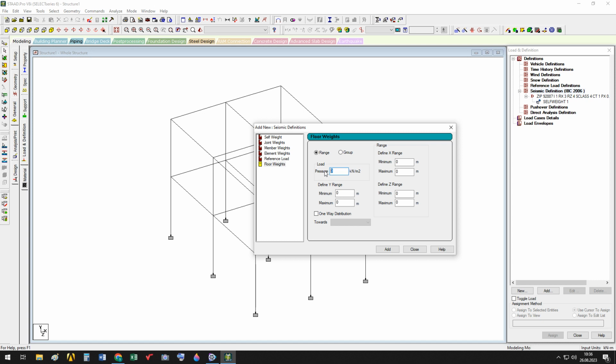Let's say, now I will show you how the lateral static equivalent earthquake load is applied by means of Staad. So the weight is given here as 5 kilonewton. I assume this value is valid not only for the first floor but also for the second floor, and my story height is 6 meters.